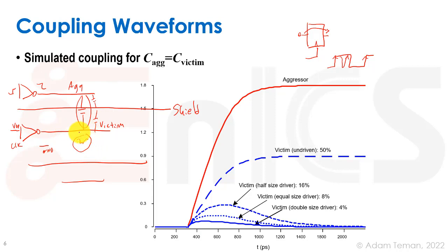But on the other hand, the clock net is also a very strong type of net, that has these sharp transitions and so forth. So it has really big drivers, and the really big drivers are going to cause victims to get a nice spike on them. So we also want to protect other nets from them. So as a secondary thing, it protects other signals from aggression by a clock net. Those are two things, and the clock net really is the most important net in a digital system.